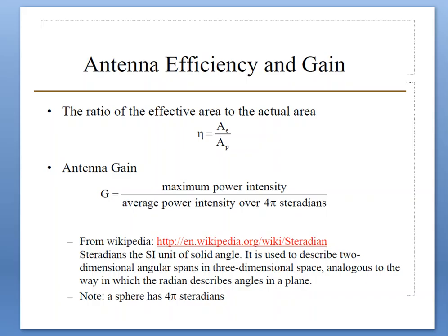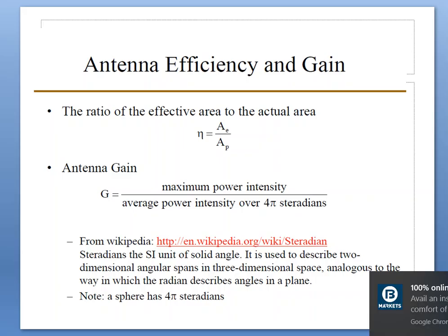In the absence of any loss or impedance mismatch loss, the antenna gain is defined simply as the directive gain. However, in the event there are dispersive and impedance mismatch losses, the antenna gain is equal to the directive gain times a loss factor to account for these losses. Here we shall assume that the dispersive losses are 0 and the impedance is perfectly matched.